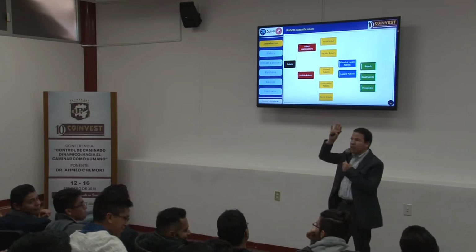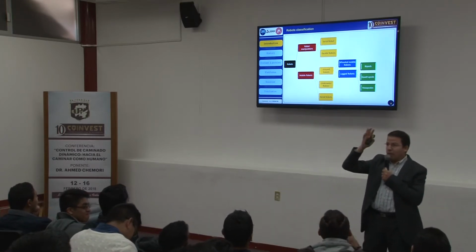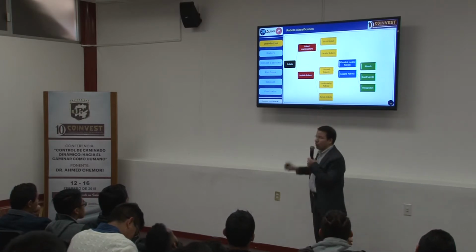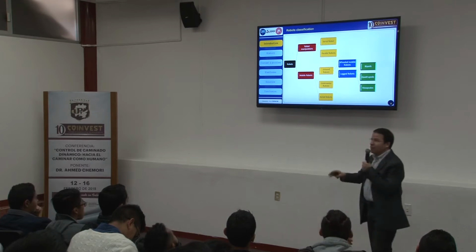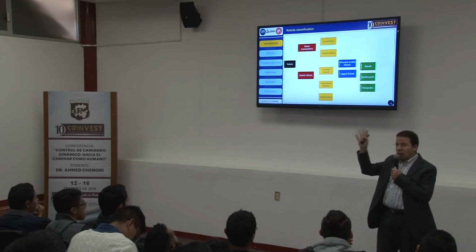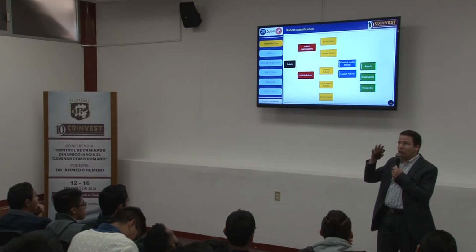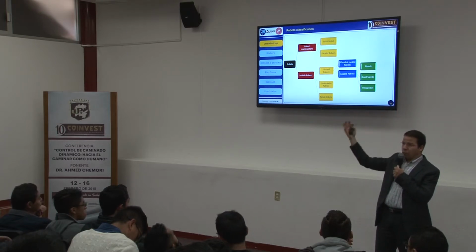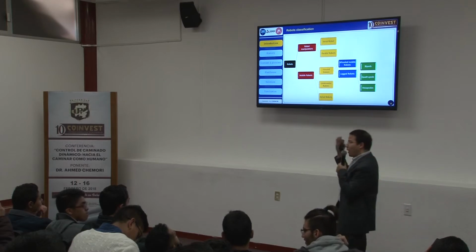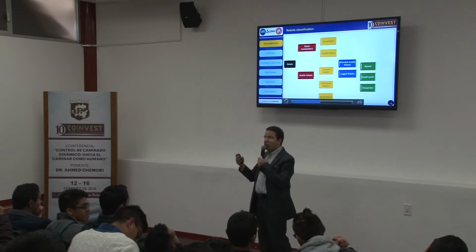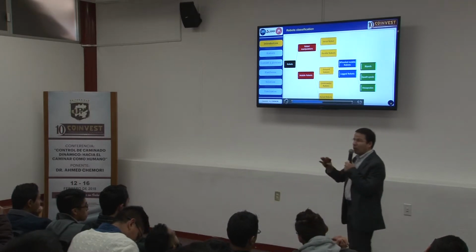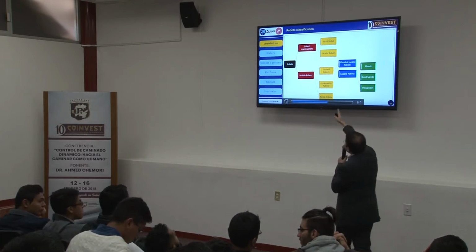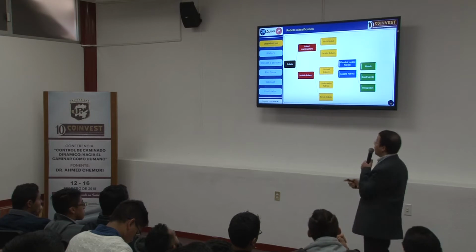The first is the class of robotic manipulator arms, and the second is the class of mobile robots. The robots in the first class are characterized by a fixed base, like the shoulder here, and the manipulator can move in space. Depending on the mechanical or kinematic structure of the manipulator, we have 2 subclasses, which are serial manipulators and parallel manipulators.